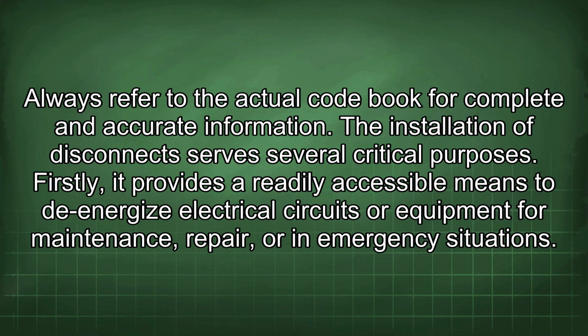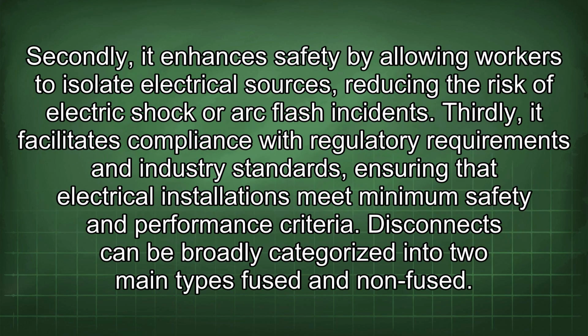The installation of disconnects serves several critical purposes. Firstly, it provides a readily accessible means to de-energize electrical circuits or equipment for maintenance, repair, or in emergency situations. Secondly, it enhances safety by allowing workers to isolate electrical sources, reducing the risk of electric shock or arc flash incidents. Thirdly, it facilitates compliance with regulatory requirements and industry standards, ensuring that electrical installations meet minimum safety and performance criteria.